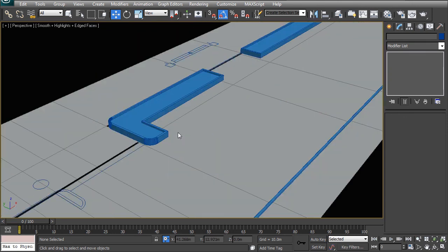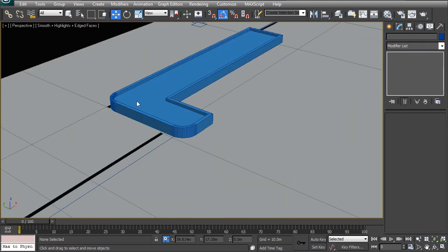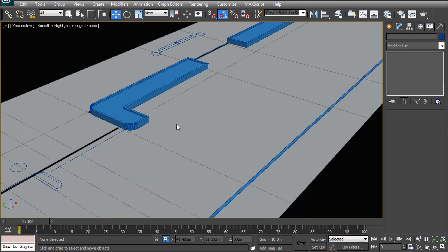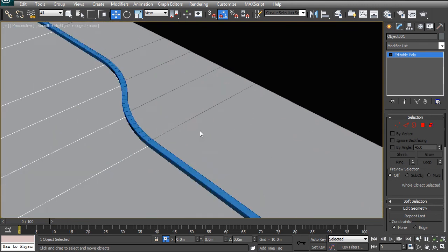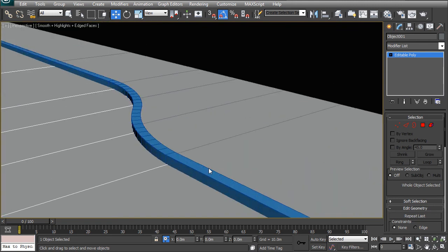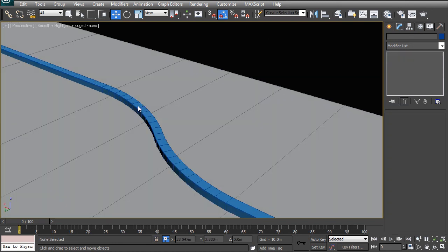We have popped up the planters. We've detached the surfaces which will be used as the greener grass or the gravel or whatever you'd like to put here. The road has been detached and lowered down, and we've also created the pavement edge that is following the CAD geometry. It's extracted from the CAD geometry directly, so we didn't even have to model these curves or redo these radiuses or work anything out. They're just directly taken from our base geometry. And there you have it.